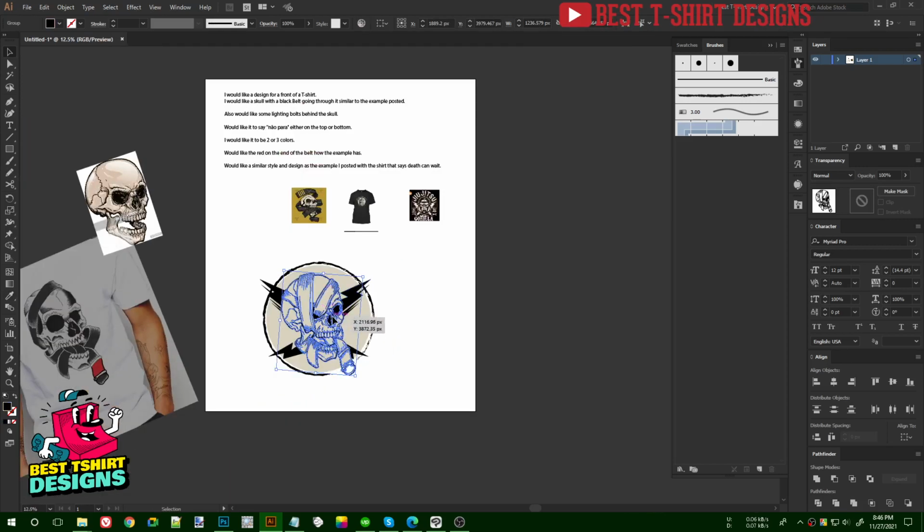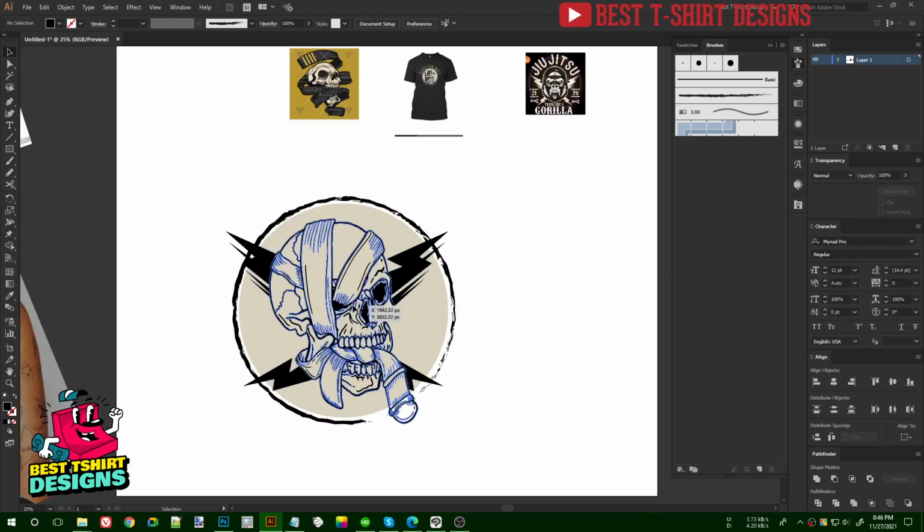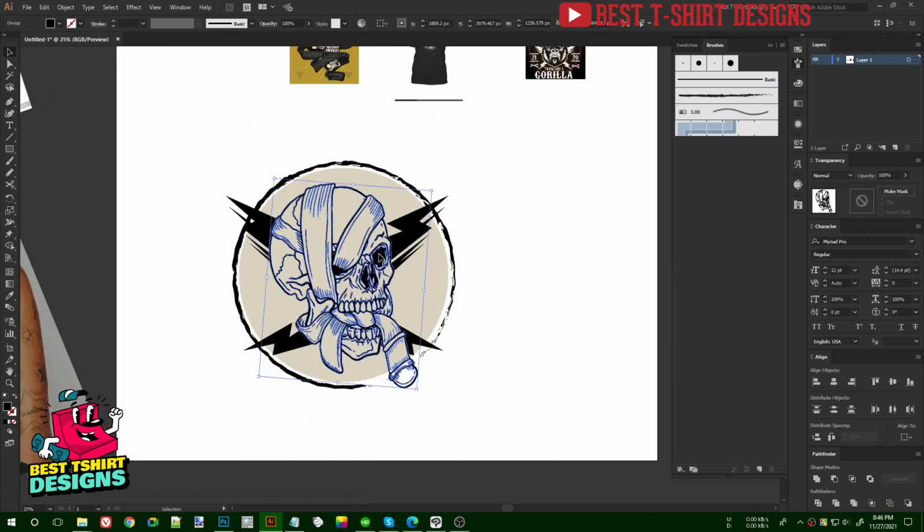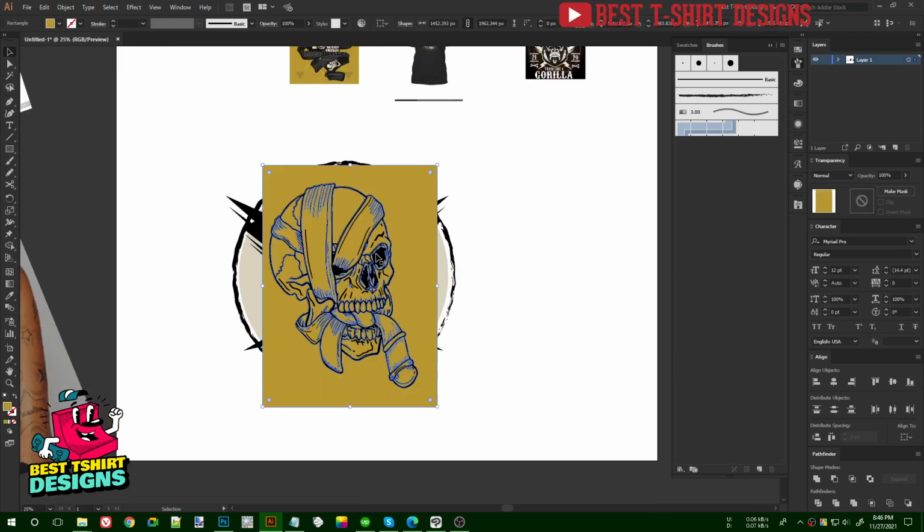Okay, before doing anything I am going to keep a copy of this one in case in any step I want to come back, so I'm going to press Ctrl B here. So this is how it is looking. This is color on top and that color in the background. So I'm going to select these two, then I will simply use trim.